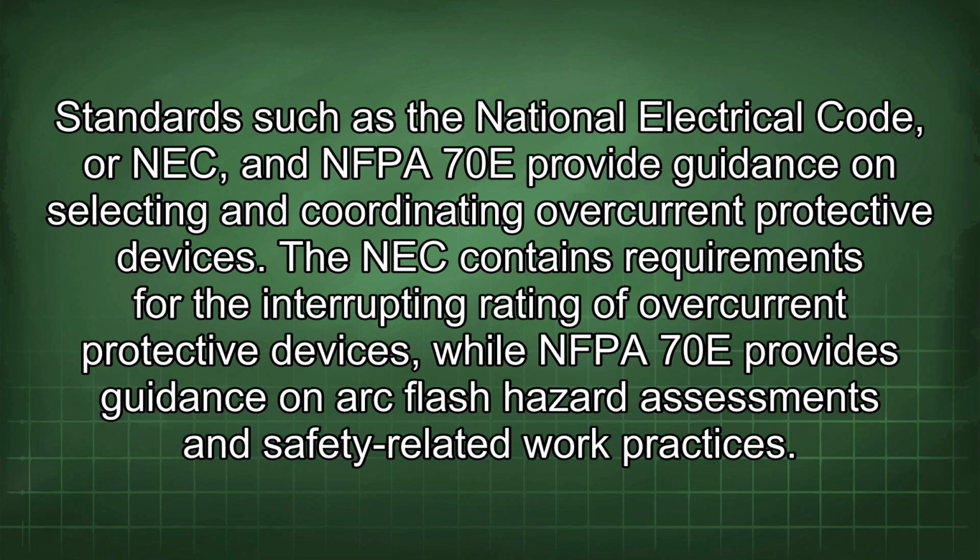Standards such as the National Electrical Code, or NEC, and NFPA 70E provide guidance on selecting and coordinating overcurrent protective devices. The NEC contains requirements for the interrupting rating of overcurrent protective devices, while NFPA 70E provides guidance on arc flash hazard assessments and safety-related work practices.